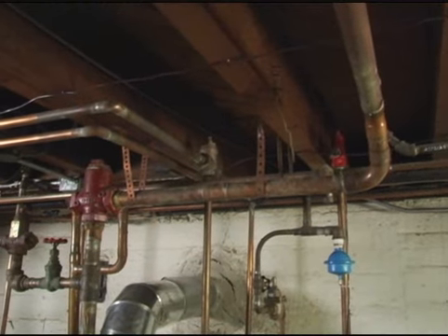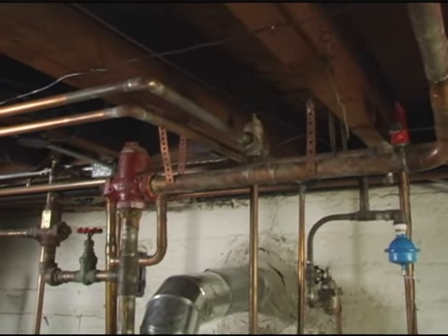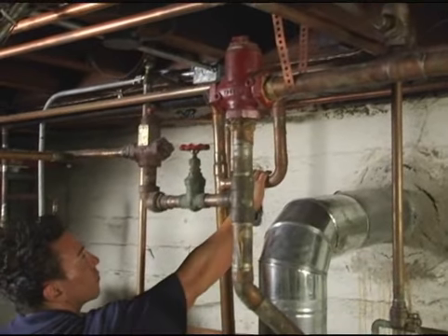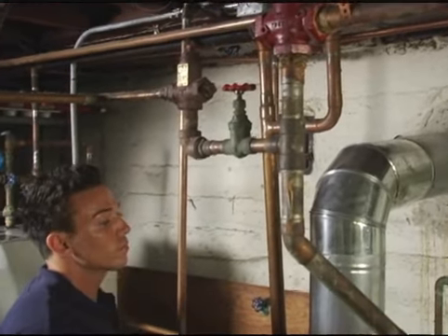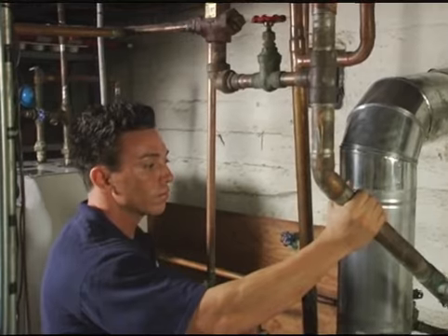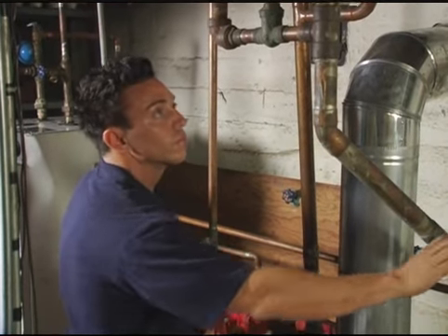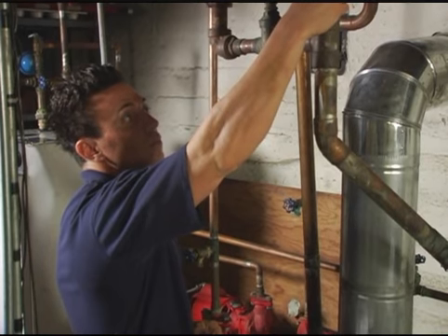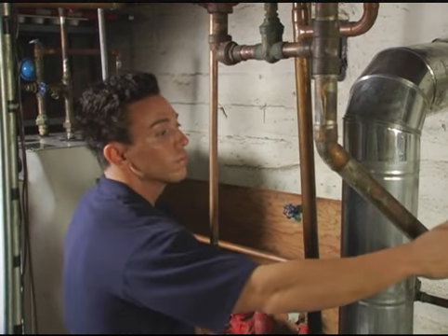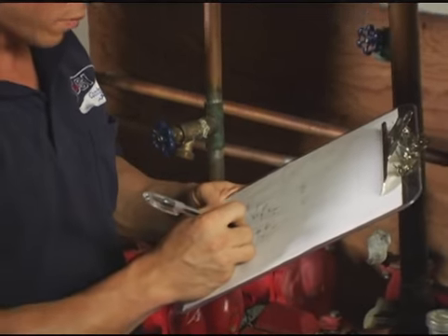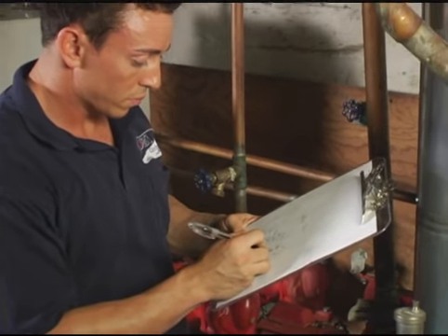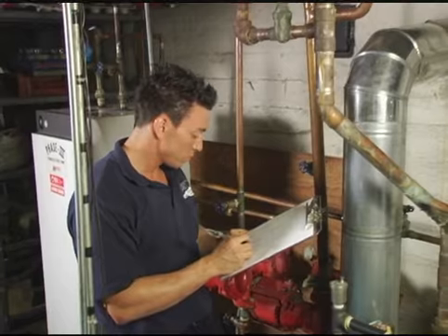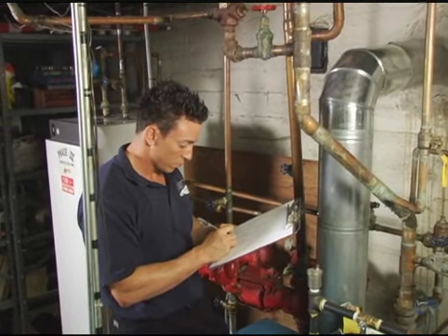A thorough understanding of the sequence of operation is also required. If a particular zone is not receiving enough heat, which pumps or valves in the system must operate in order to deliver heat to the affected zone? If the zone is receiving too much heat, what components must operate in order to stop the delivery of heat? One key to understanding the system is making a diagram of the piping. Often overlooked, this simple step can save hours of troubleshooting time.